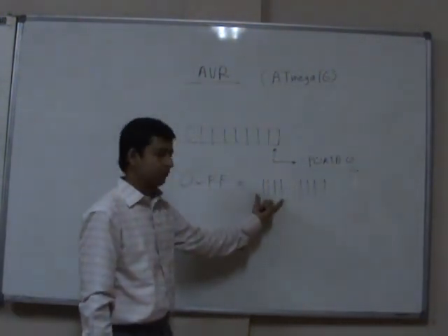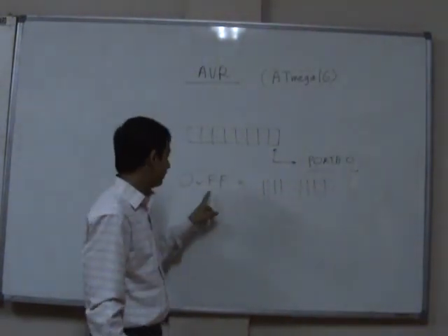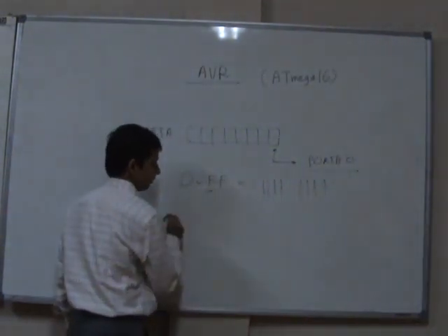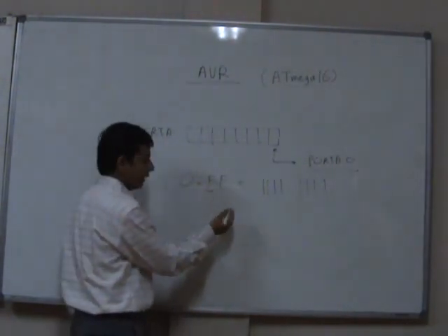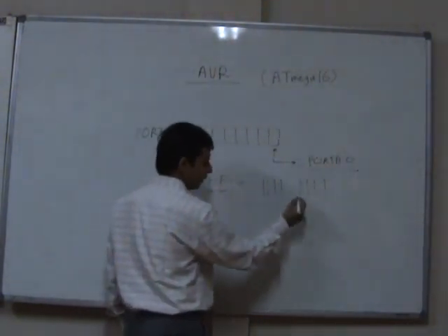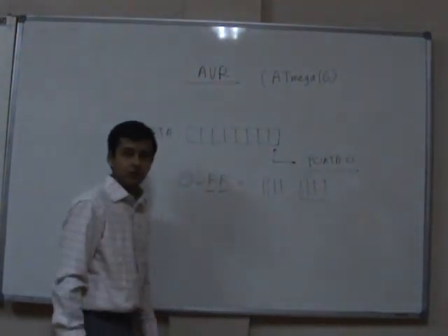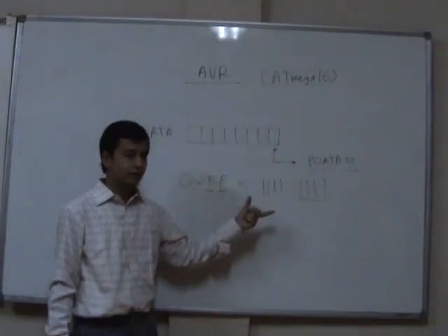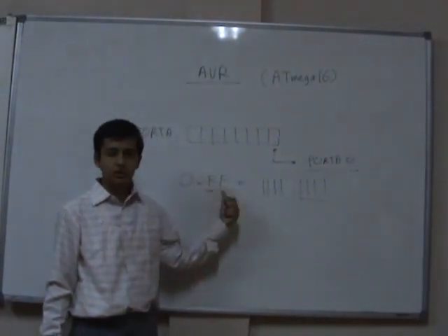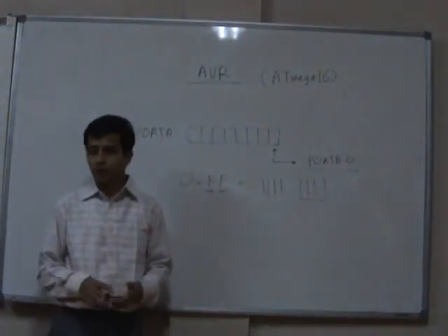The upper 4 bits of the 8-bit binary number will represent the higher nibble of the hexadecimal number, and the lower nibble of the hexadecimal number will be represented by the lower 4 bits of the binary number. So there is a direct conversion. Whenever you want to write something, you can use either notation. But then how to use this notation?